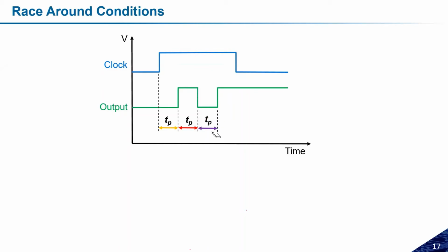So how do we avoid this problem? Either I can reduce the pulse width of this clock. If we are able to reduce the pulse width, the toggling might be avoided, but 100% pulse width reduction is not possible, because if I reduce the pulse width, the clock frequency will become very high. In the last slide we saw the clock frequency depends on the propagation delay of the next state logic, the propagation delay of the flip-flop, and the setup time, and these parameters cannot be reduced to 0.